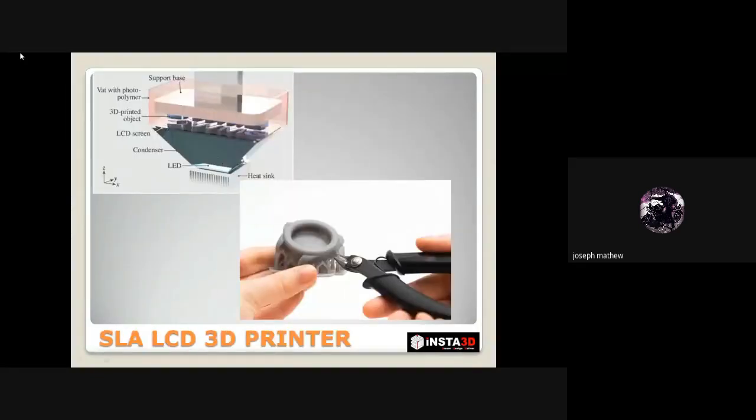So this is an LCD SLA 3D printer. This combines the benefits of SLA and DLP techniques. So here they are using an LED screen from which UV light is projected, and photopolymerization happens in the chamber. So this is the bottom up approach. The platform is on the upper side and it moves from down to up. So it's called the bottom up approach.